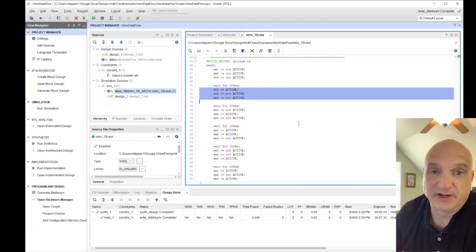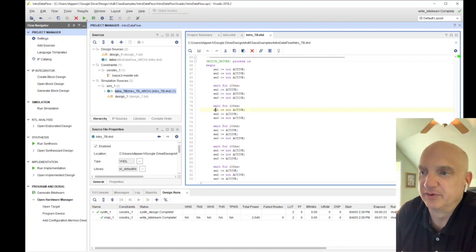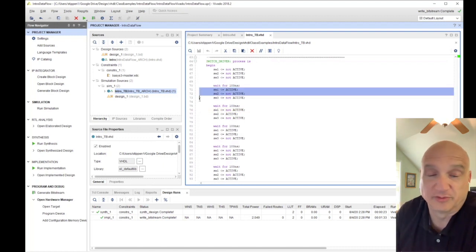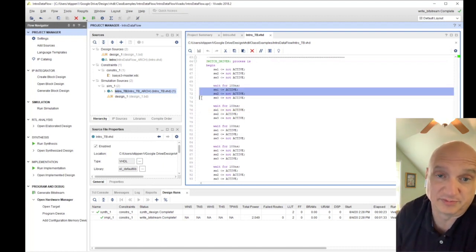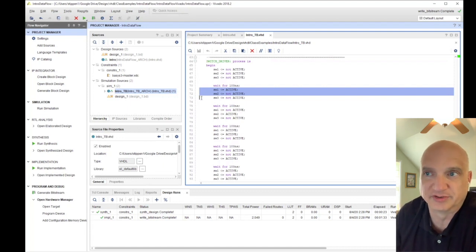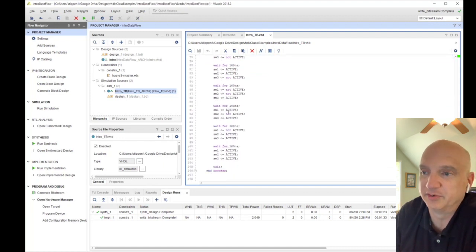And we change them now to where switch 1 is only active and the rest of them are off. We do this repeatedly 8 times so that we can test. We've got 3 bits, so it's 8 possibilities. You've got 0,0,0, 0,0,1, 0,1,0, 0,1,1, and so on. All of those are what we're going through by hand by doing this.